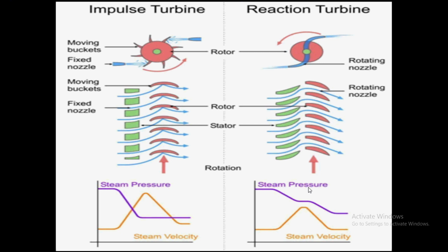So next is the trip mechanism. A steam turbine is provided with a trip mechanism operating through an overspeed governor to shut off supply of steam to the turbine. The trip mechanism is actually a safety device which gets activated upon a number of other adverse operating conditions of the turbine such as loss of lubricating oil pressure or condenser vacuum or excessive axial thrust, etc.